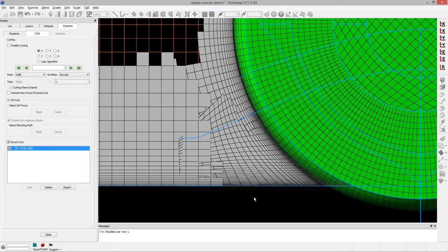So like Chris mentioned, you can do a lot with static overset cases. We can add complexity, we can bring in these wheels, we can change the ride height by just translating the entire vehicle body up and down. We could say change the weight of the vehicle and the location of the intersection of the wheel and the ground plane. And in doing that, all we would need to regenerate is that collar block.